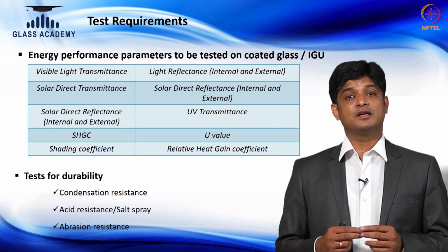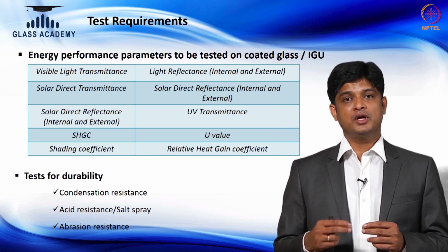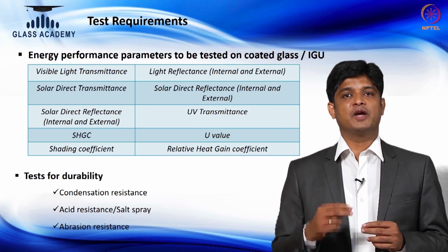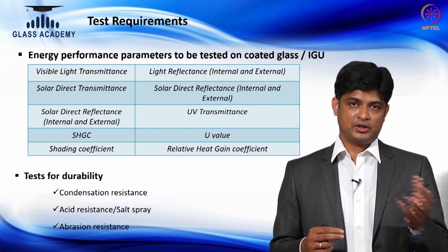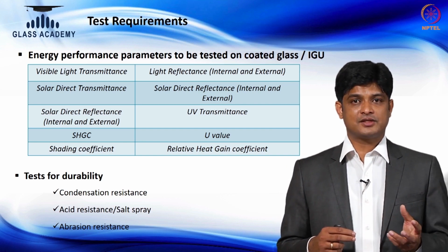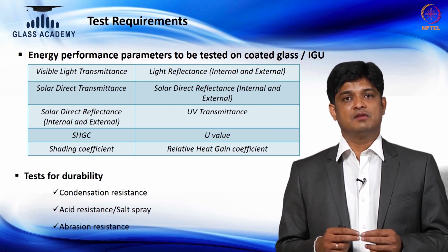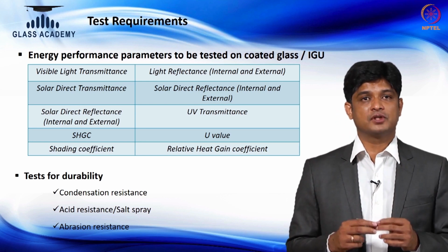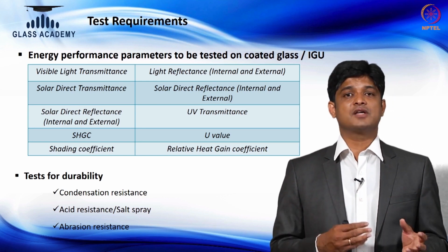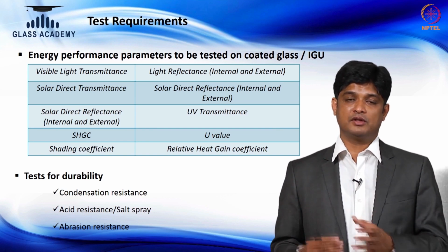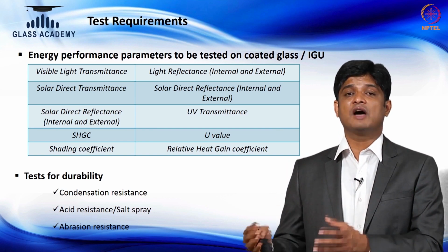Plus there are a few other durability tests which have to be done for these kinds of high performance glasses: the condensation resistance test for the coated glasses, acid resistance or salt spray analysis, which help you understand the durability, and some abrasion resistance tests, because the glass has to pass through a lot of value addition, whether during processing or even after processing.